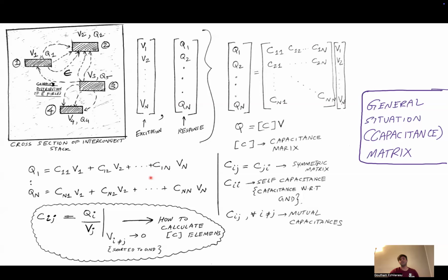So, what is one way you can think of to minimize the cross coupling? One simple way would just be to increase the distance between the conductors. Because the capacitance is going to be epsilon A over D, if you increase D, the capacitance is going to go down, and the cross coupling is going to go down. Another method would be to use a dielectric material with a low dielectric constant, and that is a way to reduce this kind of cross coupling capacitance.